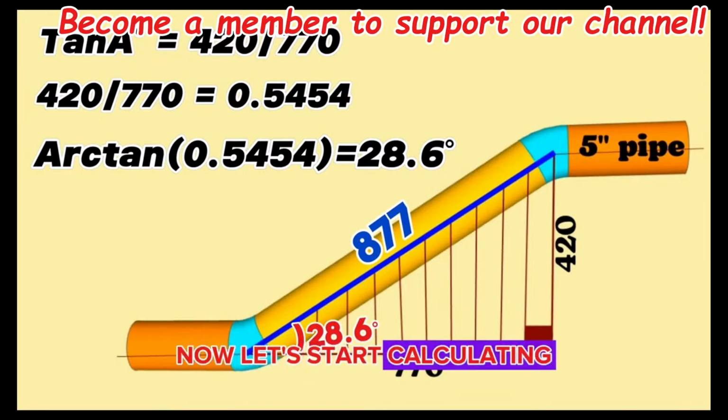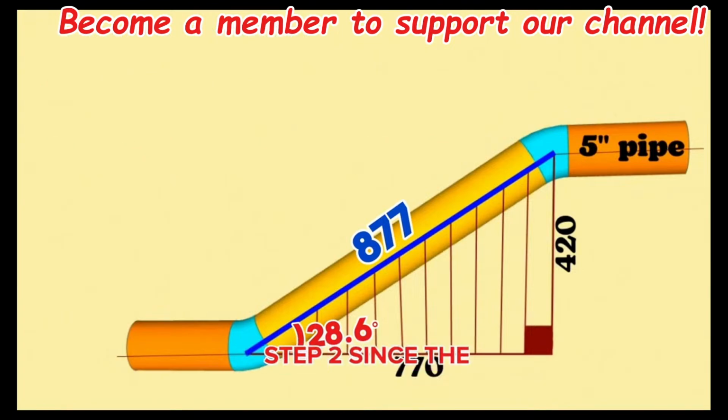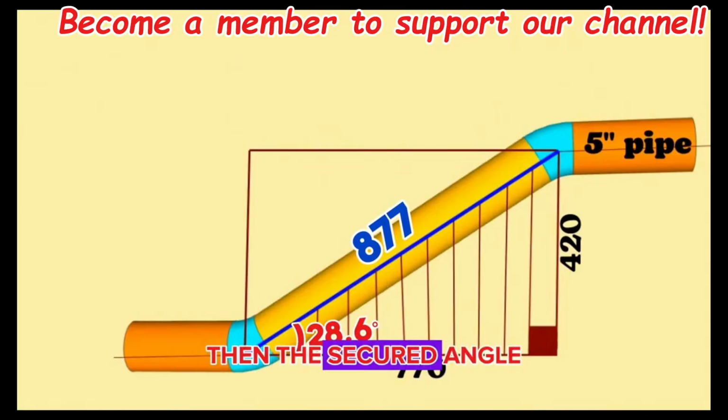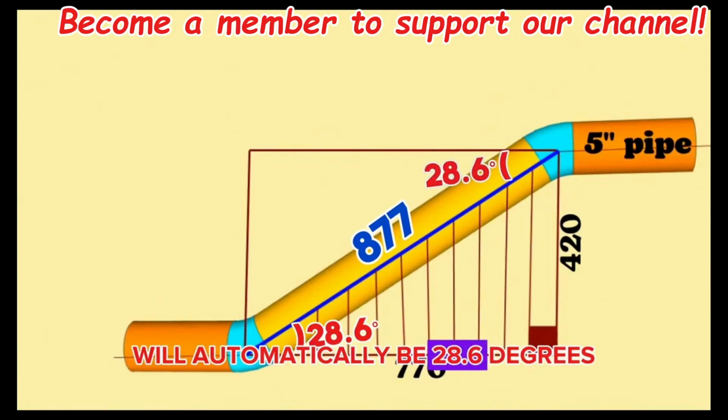Now let's start calculating the cutting angle of the second elbow on the top. Let's go step by step. Since the pipeline moves in the same plane, let's complete this right triangle into a rectangle. Then this acute angle of the upper right triangle will automatically be 28.6 degrees.